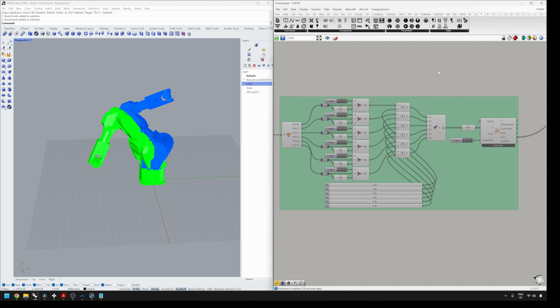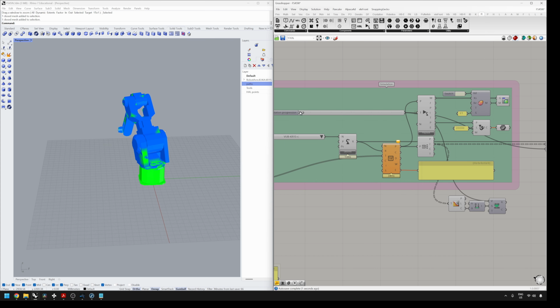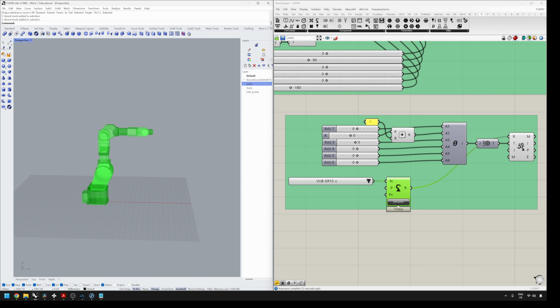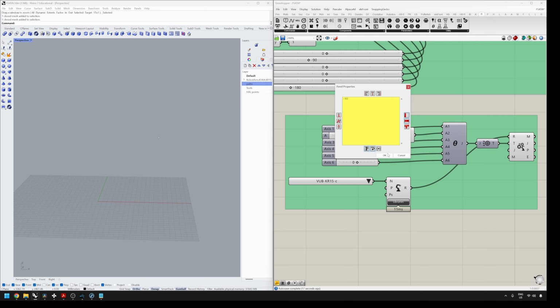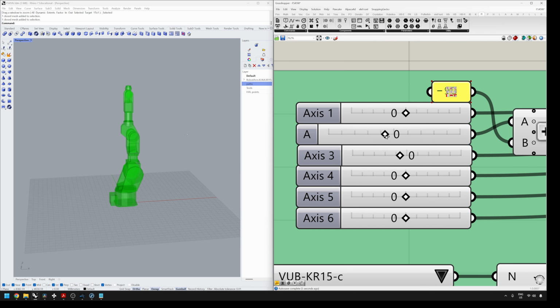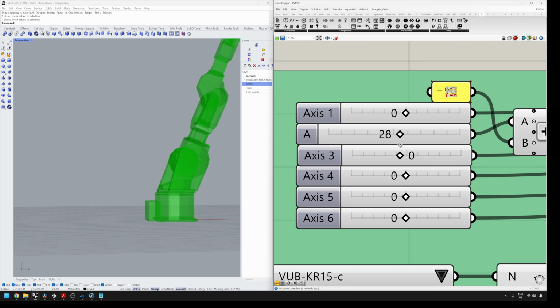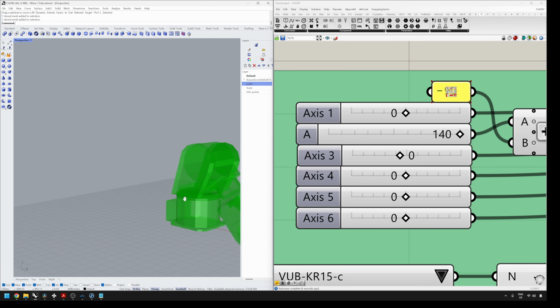To make the HAL Robotics result match the robot's program simulation, I found that joints 1, 4, and 6 required sign inversions. Joint 2 required a minus 90-degree offset, and joint 6 also required a minus 180-degree offset. Some of these changes appear to correspond to the plugin's internal 0 position. For example, when creating a separate kinematics definition in the robot's plugin, joint 2 requires a minus 90 degree rotation to match the expected Kawasaki null position. Joint 6 may similarly use a reference position shifted by 180 degrees.